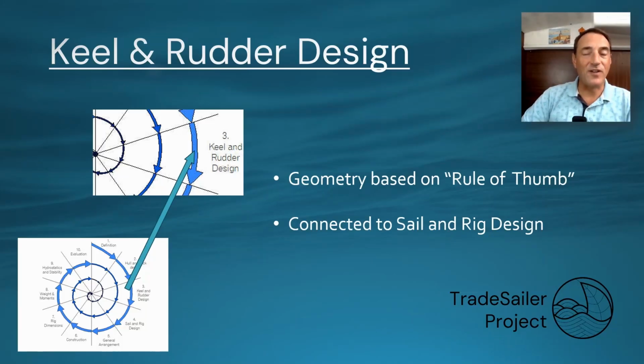So let's start with the keel and rudder design. The keel and the rudder geometry is based on experience, rule of thumb numbers, experience numbers. And they're based on, for example, sail area, lateral area on the water plane, displacement, etc. Different factors we use to determine in this stage the dimensions. And as I said, they're connected to the sail and rig design. So we balance the keel and rudder areas to the sail areas. By giving them the right balance, we stop the boat from turning into the wind or falling away from the wind.